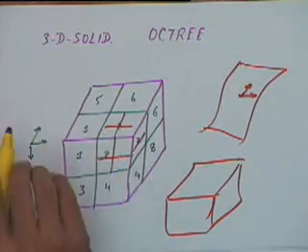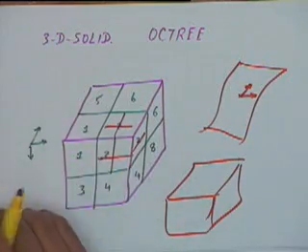Some algorithms are also available for getting the equation of a model represented by an octree model, because that is quite commonly needed. The algorithms are available, but they are complex. They will do some kind of fitting between the cuboids, each cuboid being a 0 or a 1. They will use a regression technique to get the equation of a curve, but it is complex. So between these three techniques one can switch from one to the other, but at the cost of time.